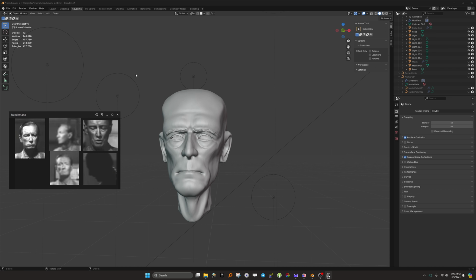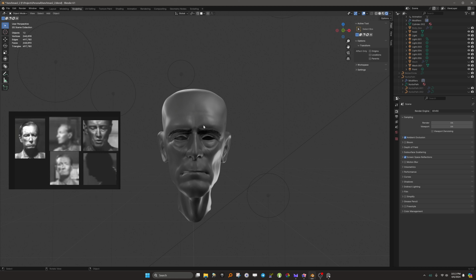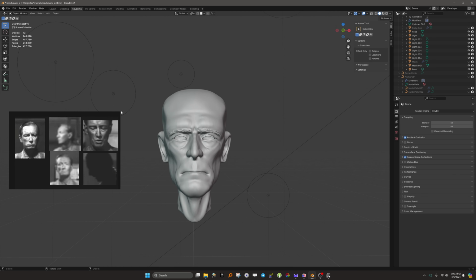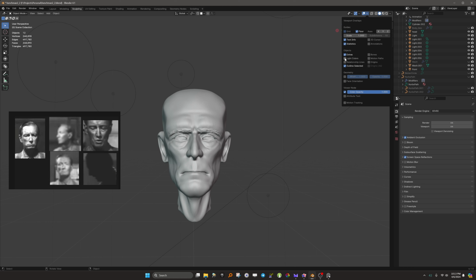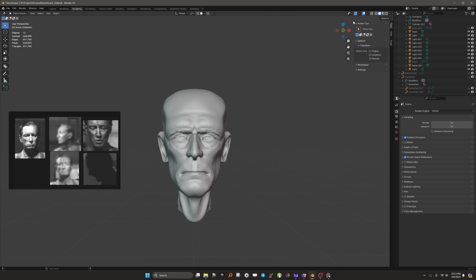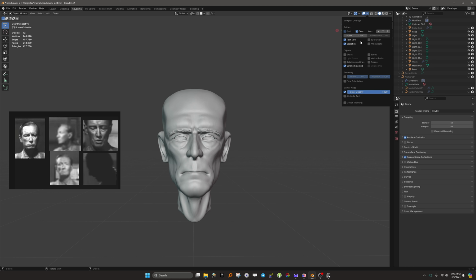The first thing I want to do is get rid of all these little lights. This isn't the end result, of course, because I'm still sculpting it, but these are all the lights that are remnants from the other guy, what's illuminating him. But we don't need to see them. So the way that you get rid of them is you go over to the viewport overlays and get rid of extras. The lights and the camera will disappear, but you might still see lines that are visible.